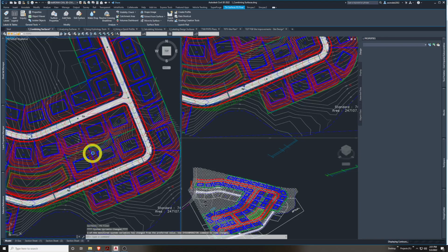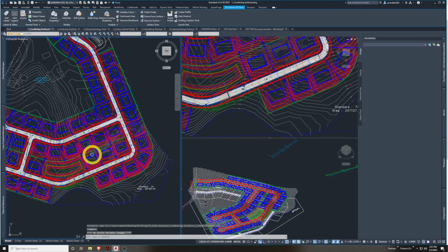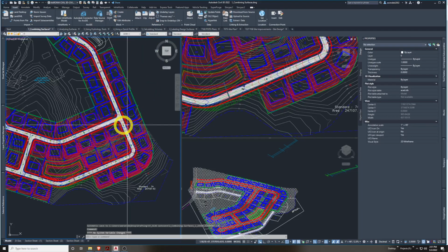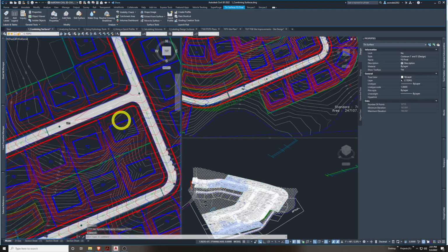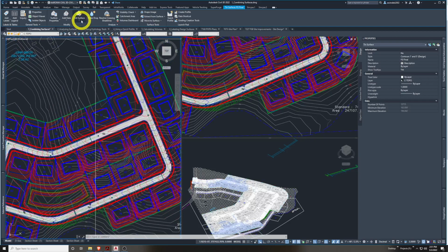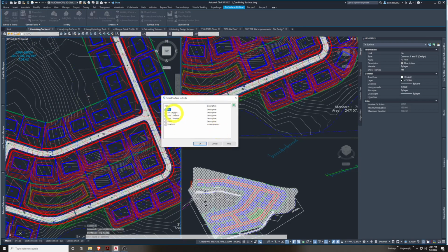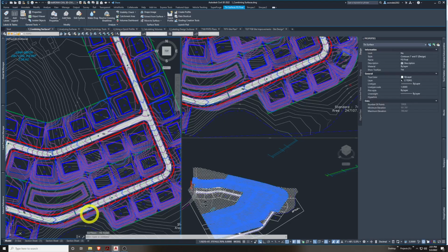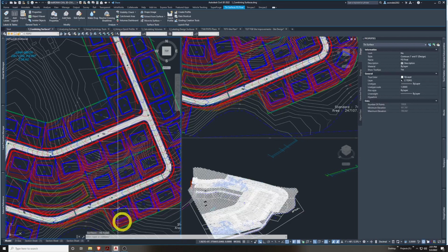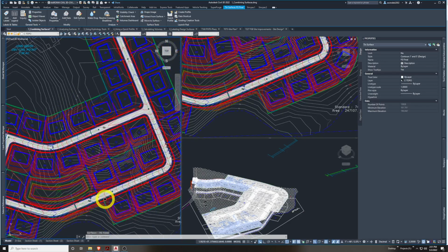We're going to add one more piece of data to it though. So if you still have your surface selected, it's totally fine because we're going to add one more operation in the paste function, but let me select it again and go to edit surface, paste surface. We still want to add this surface here, this lot daylight surface. We'll hit OK. It's a small little silver surface on the outside, as we can see it filled in here, daylighted in some areas on the exterior of the lot.